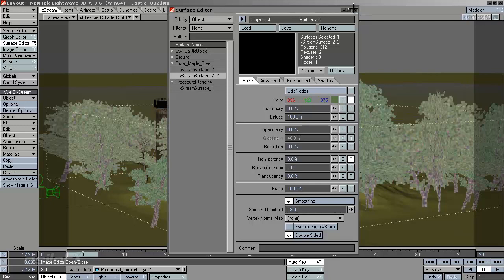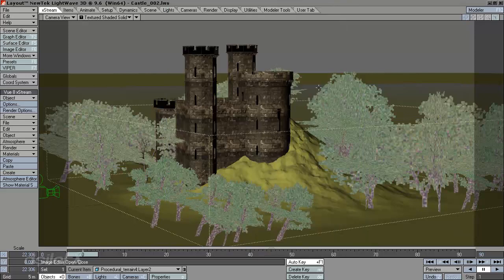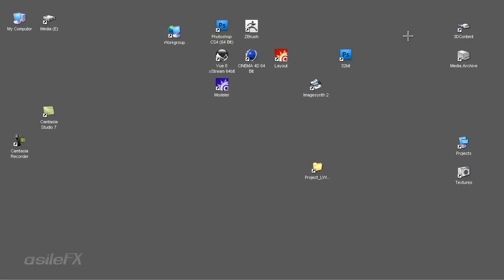Now, those are automatically saved to wherever your operating system temporary directory is set to. Which means the more of these proxy objects you have in your scene, and going back to what I was talking about early in the training, having the separate content on a different hard drive from the operating system hard drive can really improve performance. What you can do, and I'm just going to show you this for Windows, which is what I'm using, to be able to set up a separate temporary folder, because it is just going to save to whatever the temporary directory is, which is by default set to the operating system temporary directory within that hard drive.